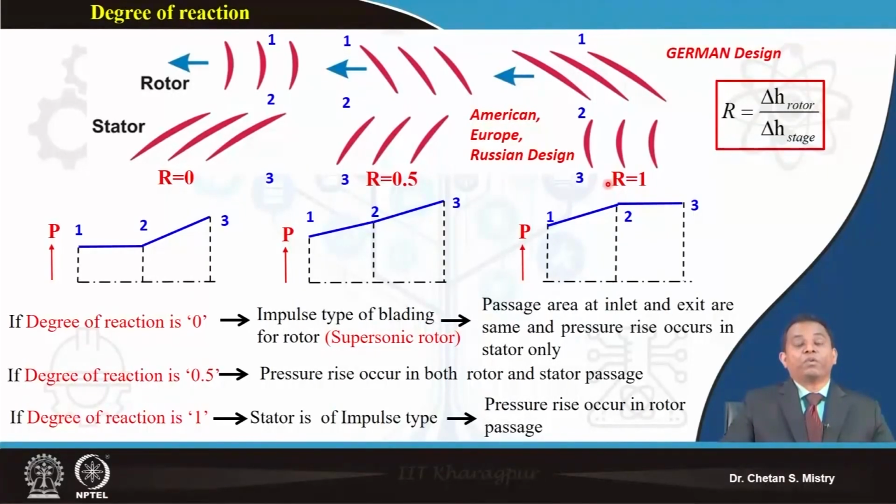When we look at our velocity triangle, you may realize near the hub region our degree of reaction will be coming low, because my peripheral speed is lower. And when I am talking about my degree of reaction near the tip region or my shroud region, I will be getting my degree of reaction coming to be large.